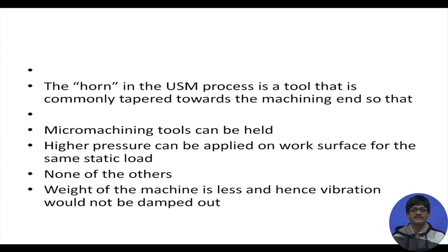Weight of the machine is less and vibration would not be damped out. This is also not the reason for which it is commonly tapered. It is commonly tapered for a completely different reason. That is amplification of the amplitude. The amplitude is magnified at the tool end of the horn due to its tapered shape.